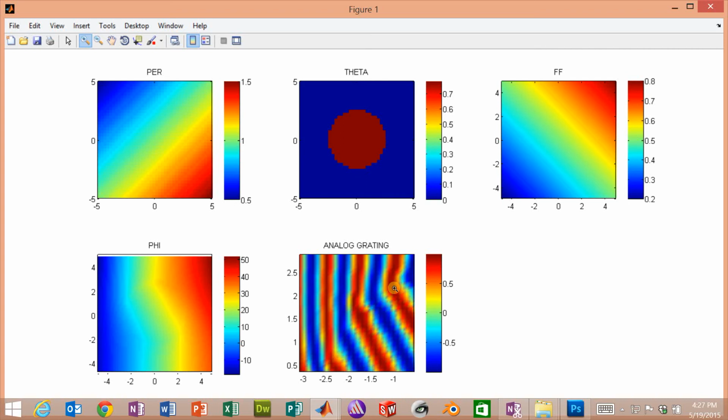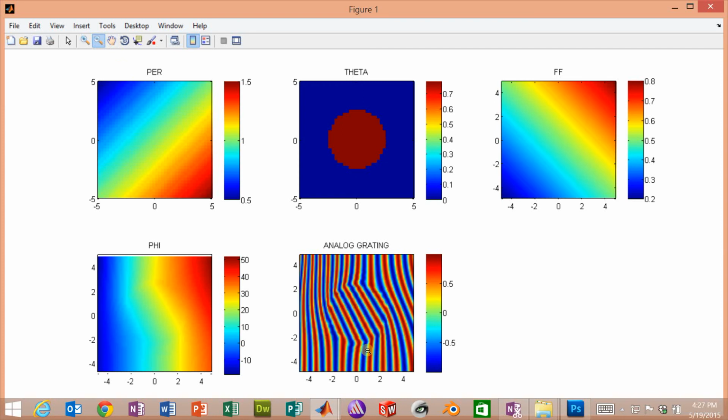We not only have a somewhat low resolution grid here, but we see pretty sharp kinks. And it turns out we can clean this up a little bit by blurring our input data. So we can fix this just by blurring theta. Notice this is kind of staircased. It's on a very low resolution grid. We want that for speed. We could make our low resolution grid higher resolution to fix that, or we could just slightly blur our theta function. Let's try slightly blurring it.